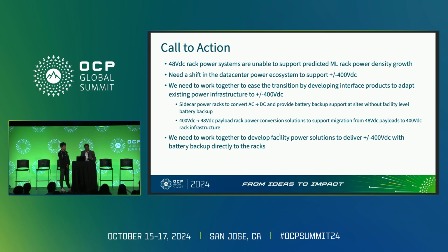and hopefully you caught one of the themes of the talk, we want to free up the space inside the hall as much as possible for the compute, whether it's the chips or the racks themselves. So if we can figure out SSTs or transformer rectification units, whatever they are, to be installed outside in the electrical yard, including the batteries, because now you have a DC bus, you could directly install a battery on it, and really allocate that space in the hall for the racks. That would be the ideal way to go.